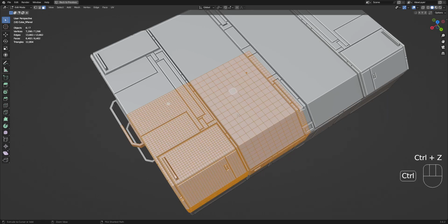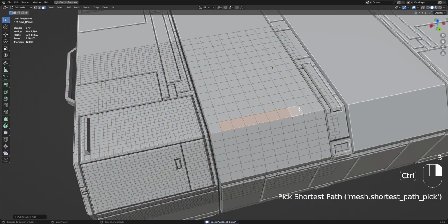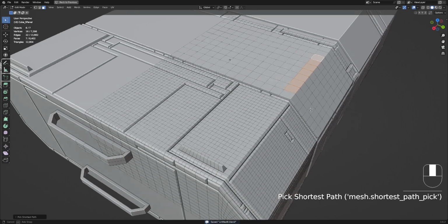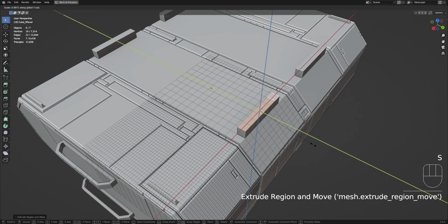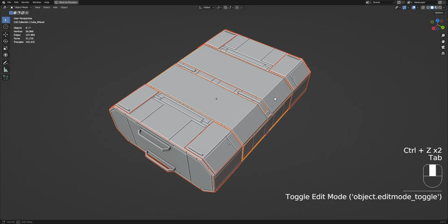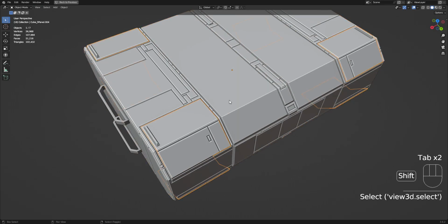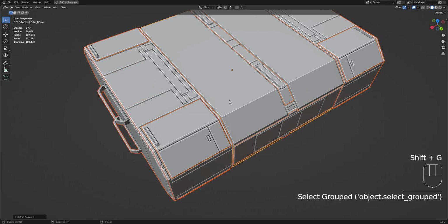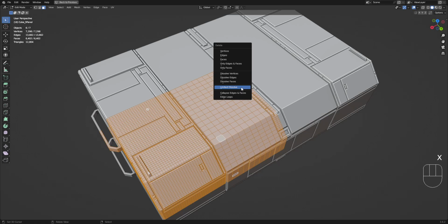But if you want to keep the quad structure, so you can easily model manually and put in some manual details after the randomization, which is easier with a quad structure, and then decide to economize the resolution afterwards, then you can just select these meshes and go to edit mode, select every face, and use limit dissolve.